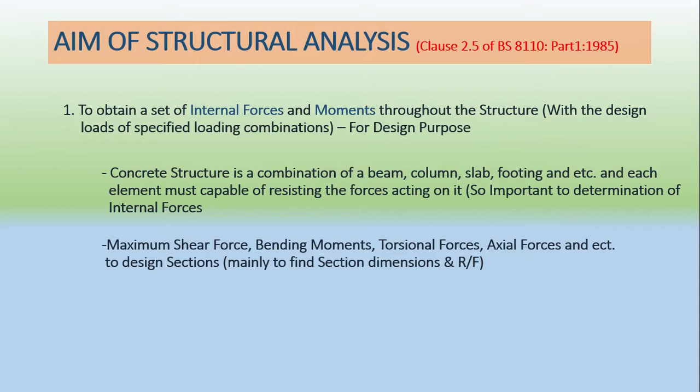A concrete structure is a combination of beams. You know that any concrete structure, that means any building, consists of beams, columns, slabs, and also footings, piles, and so many things like that. To design those sections, you have to have internal forces, not the external forces, but we use the external forces to calculate the internal forces, which are shear forces, bending moments, torsional and axial forces.